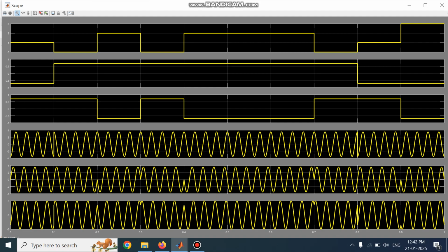So this is how each integer is mapped into the corresponding gray code, and then represented using 4 different phases: 45 degree, 135 degree, 225 degree and 315 degree. So this last waveform represents the QPSK, quadrature phase shift keying modulated signal with 4 different phases. So this is about QPSK modulation using the Simulink tool. Thank you.